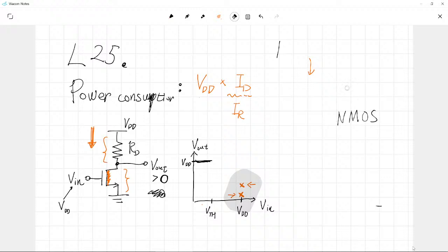So then when you have a look at this resistor current IR, how can you represent it? That is exactly given by, here we have RD, and in upper part we have VDD minus V out. That is the exact relation. And now we will say an approximate relation. What is the approximation? Yes, VDD is given, and V out we don't know.